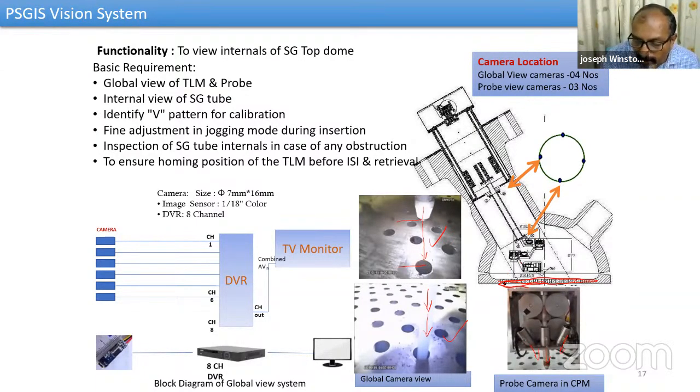Mechanically it is coupled through the flange, and then it comes through this for the reference of the robotic system. Though the robotic system is working very close to this, the mechanical route is through this, which means a lot of fabrication comes into play. One is the manhole, then the flange, then our system, which is a ball screw mechanism. Any slightest error in the system can cause a huge tilted operation of the robotic system.